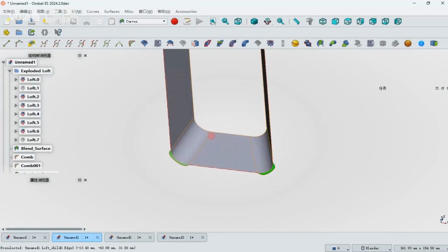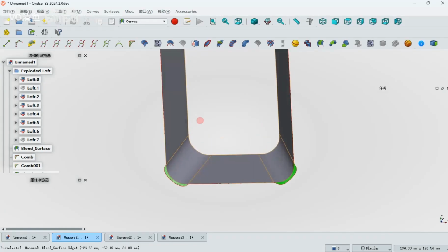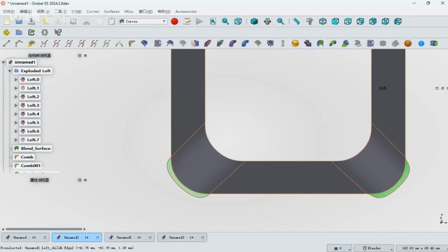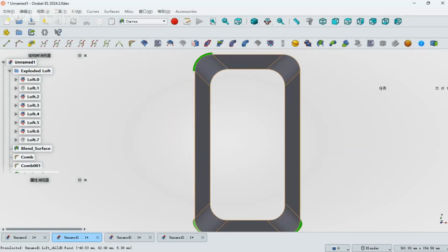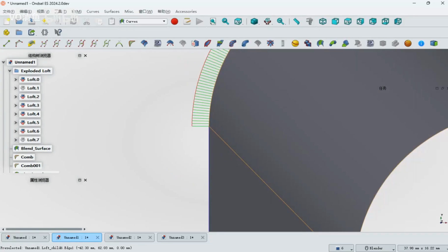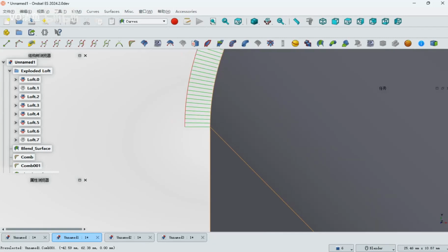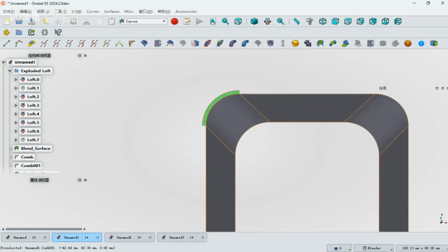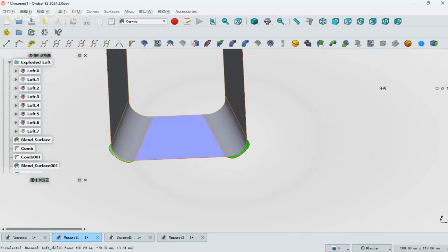For the next component, the task is to repair a fillet. As mentioned in the fillet repair video, for some parts with higher requirements, you might need to achieve a high-quality connection. Typically, if there are no specific requirements, when we run a combo check on this area, we can see the tangency condition. Regarding the relationship between curvatures, it's G0 continuity. To repair the surface, we still use the Gordon surface to create a transition, a common surface connection.